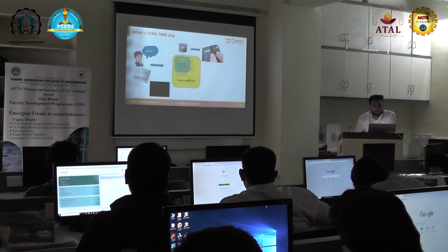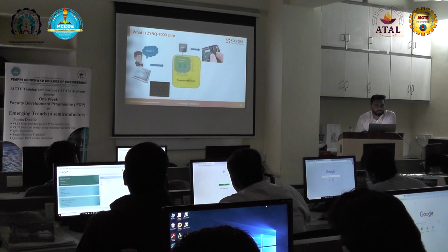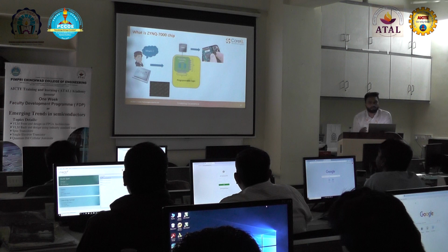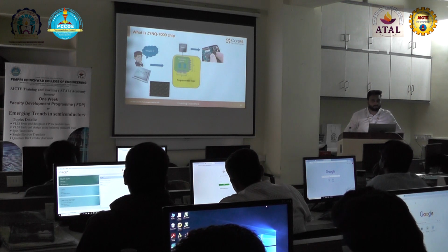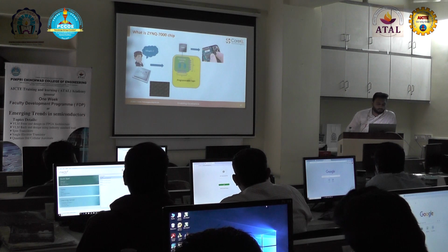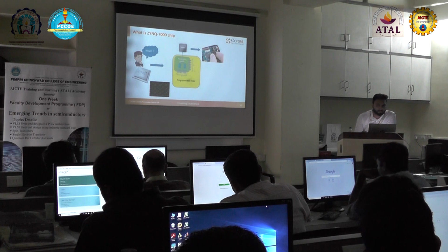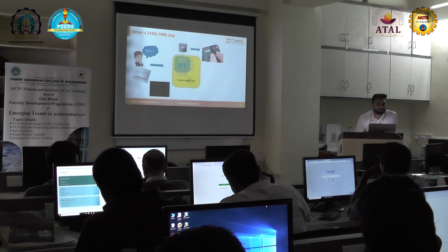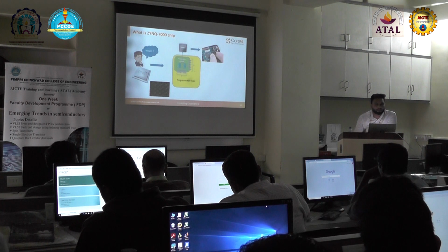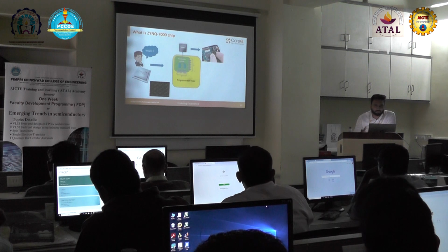So there are two series, A and R. Here we are using the A9 dual processor. So it has A and R processor, two different series. A is for application, R is for real time. So if you are selecting the APU, the application processing unit, for your application, and you are not going to do any real time project, then you are going to select the A series, which you will have in the Zynq. In the UltraScale Plus, you will have MPSoC, meaning multi-processor system on chip.